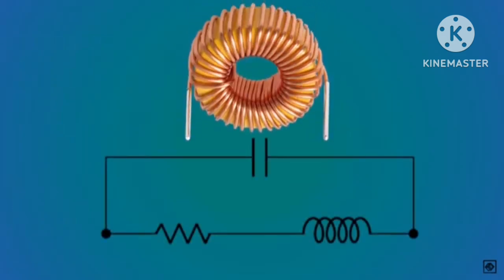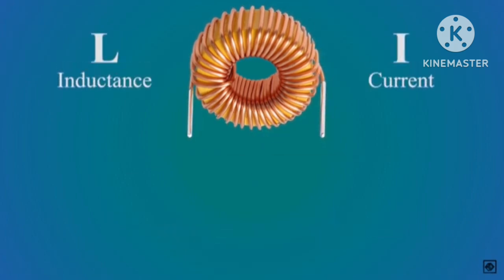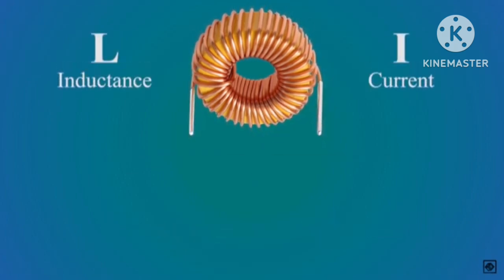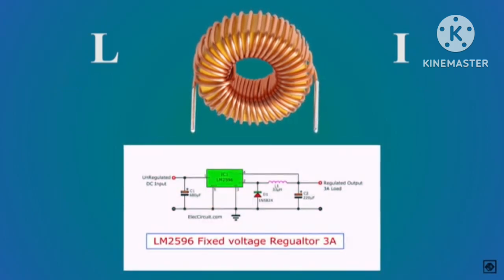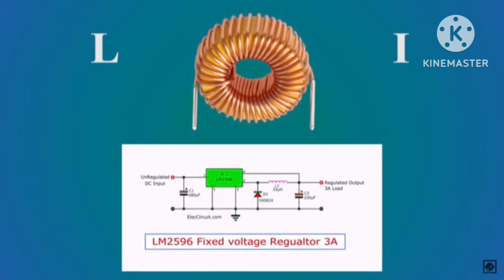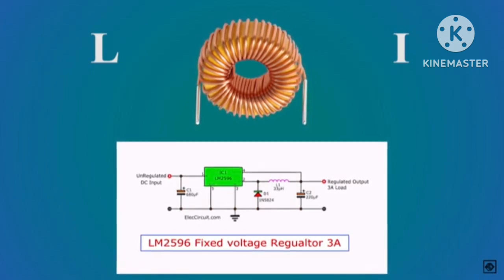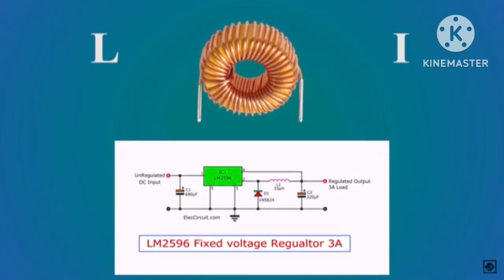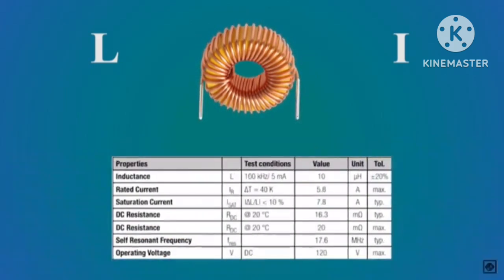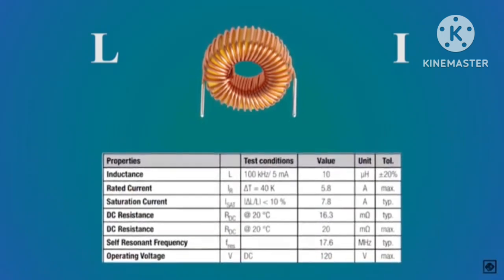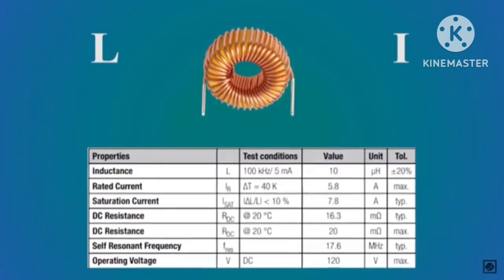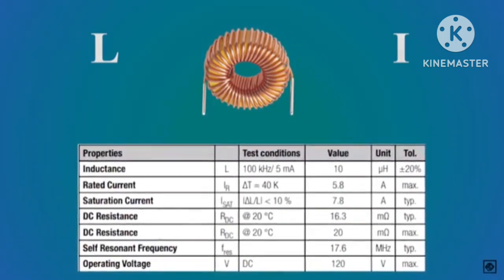The equivalent circuit diagram of the inductor is the same as that of the resistor. Calculations of required inductance are pretty complex and it depends upon the situation they are being used. Hence, check for values in the circuit diagram or IC datasheets or try some inductors. With inductance, you should also look for the maximum current and the magnetic saturation current of the inductor, and do not exceed it. For more details always look in the datasheet.